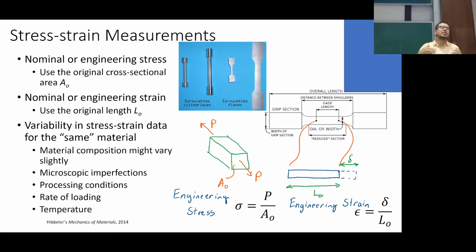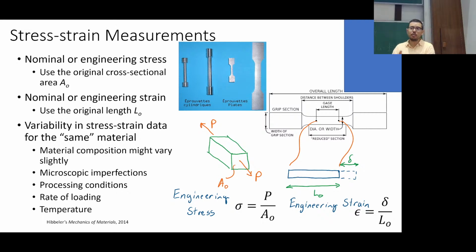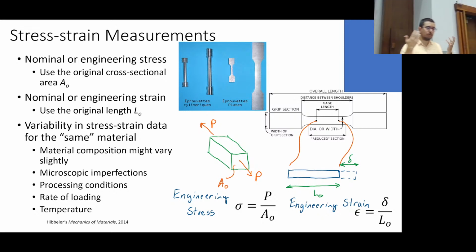What we do instead is say, the engineers in the back room think that it will really only support 100 newtons in tension, for example. But with the jumping and the impact that we expect, and the variability in the weight of the users, we're going to give it a safety factor of 3. That's pretty high, but not uncommon.